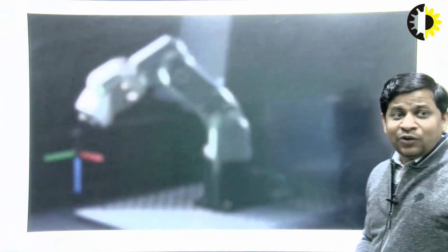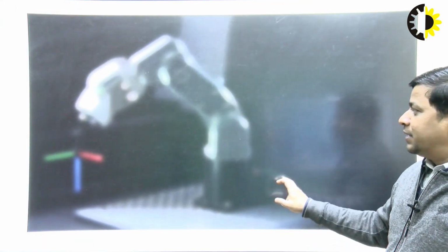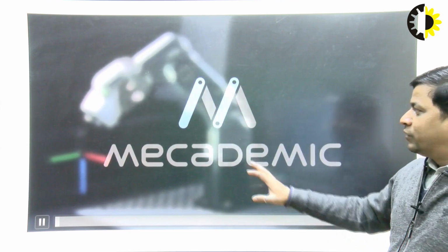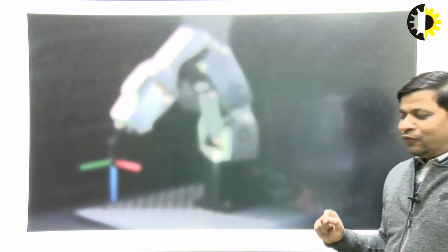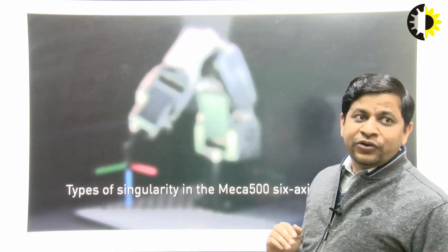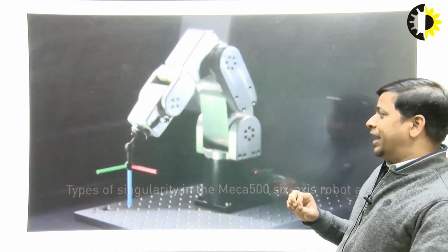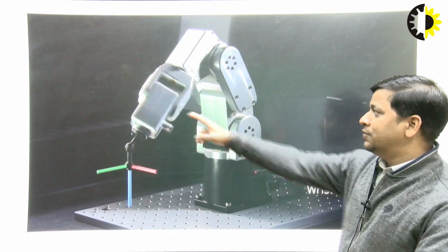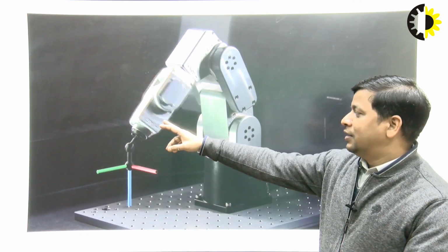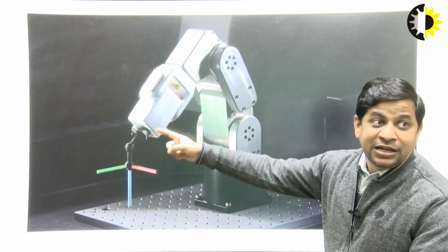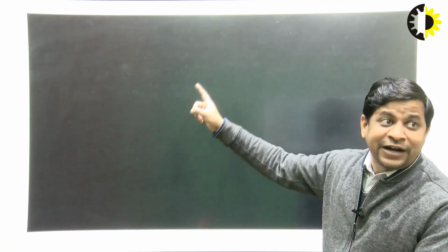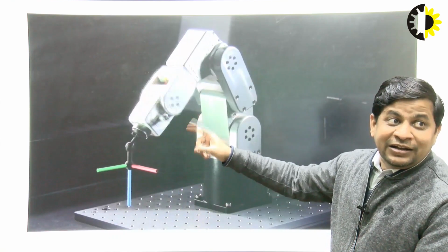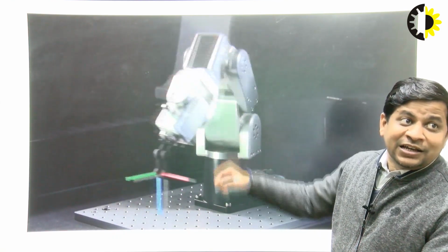So let's quickly watch one video where you can see all kinds of singularity happening, and when a singularity comes across during jogging, the robot tries to avoid that particular position by moving its axes at very high speed. So if you observe, this is alpha 5 where wrist axis singularities are there.